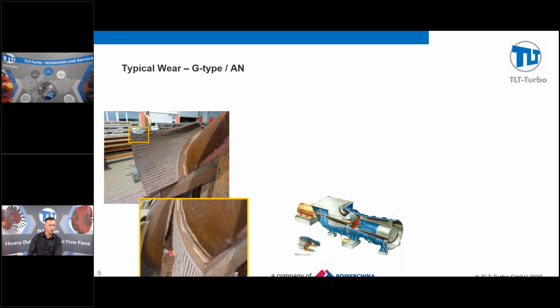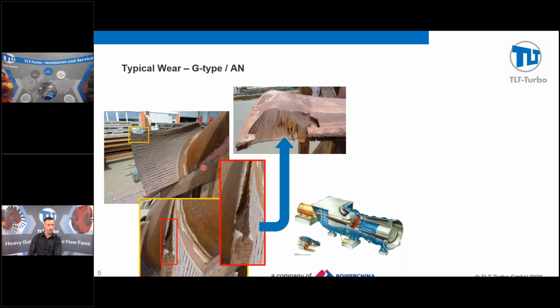And what you're seeing is the erosive material, the media, has actually chewed through the whole leading edge wear protection, or the weld-on or the hardened material, and it's got into the base material. And what it's doing is it's channeling and grooving and removing the material in the leading edge of the fan blade. And as we look at this from this angle, not so bad, but on a further inspection, you can see that there's a lot of missing material. And we'll step to another angle and you'll see that it's even more aggressive. But then when you look at it from the back profile of the blade, you can see how much material is actually lost. So once it actually broke through the surface, it started aggressively working its way through this system.